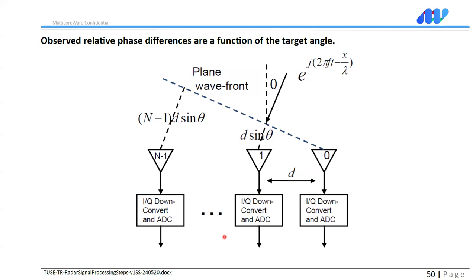However, if the array is not uniform, like sparse arrays that we're going to analyze in special topics on radar presentations, we're going to see that it's not that easy. We will use DFT and some other versions of it, especially when your array is not planar, but conforming to a non-flat surface. Then you have the conformal arrays.